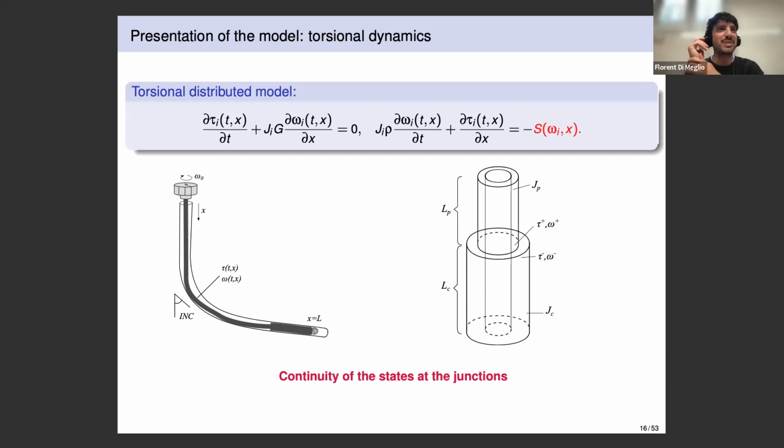Okay, so now you have to include not only axial and torsional, but also the hydraulics. Another thing you may also consider is that even if you are rotating and not moving axially, you may have a rolling of the pipe on the side, and then it slides. When you are rolling, you are in static friction conditions, and when you slide, you are in kinetic friction. So the lateral movement while you are rotating is influencing your results. But that's for the next interesting topic. Yeah, next decade of research.